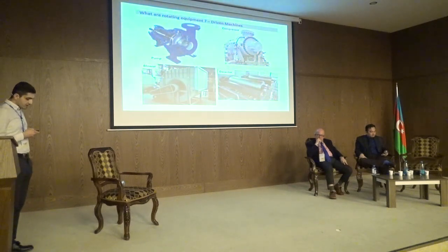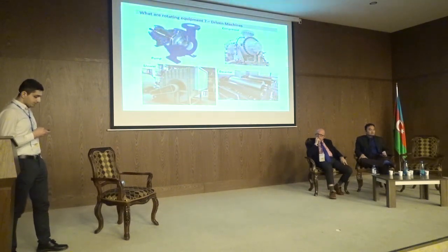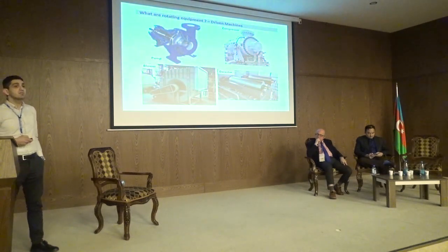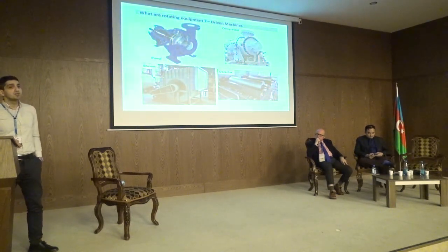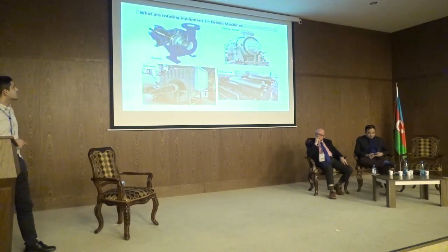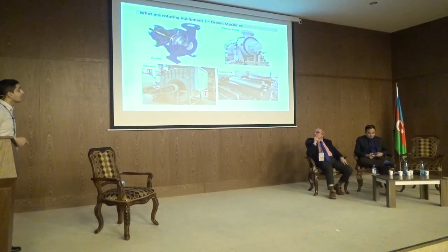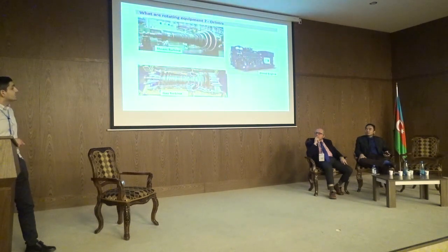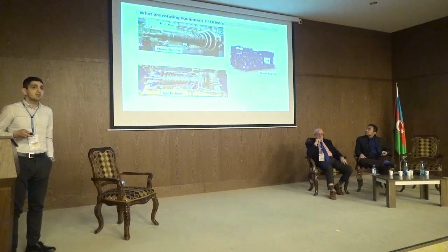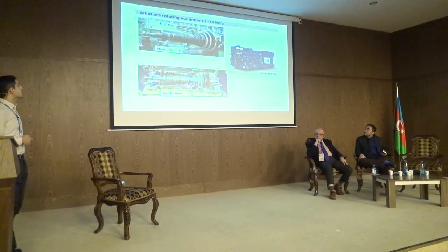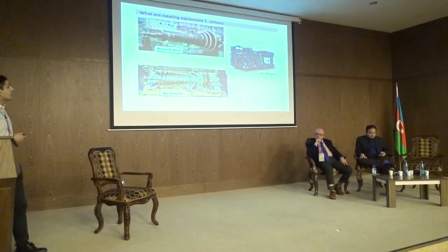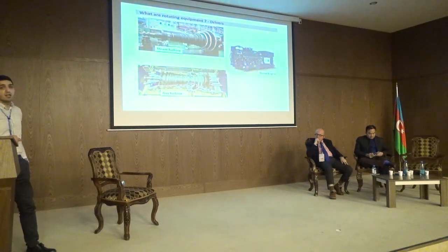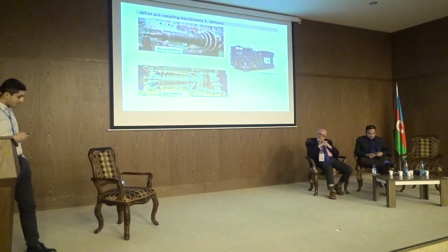These are the typical examples for the driven machines. The driven machines are the machines which impart energy into the fluid. So pumps, compressors, blowers, decanters are good examples for the driven machines. And then we have the drivers, which are used to drive the driven machines. These machines are typically steam turbine, gas turbine, or diesel engine. They are meant to extract energy from the fluid, yeah?